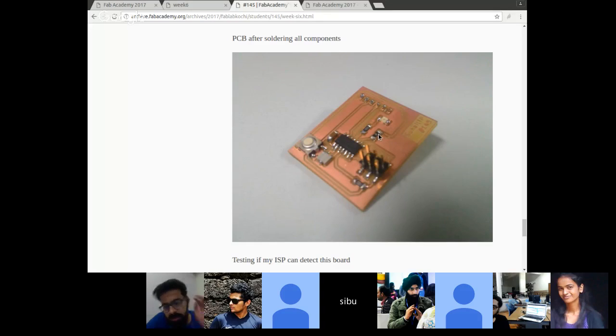Right, so you add a pull-up resistor. You read about pull-up resistors on Google? No, he is using internal pull-ups. Okay, internal pull-ups. I thought he tried using external pull-ups. No. Since this was a mistake, I just removed this. Actually, this was a 1K resistor. I removed it, connected a 0 ohm resistor to short this, and then I used internal pull-up resistors. Okay, not an issue.